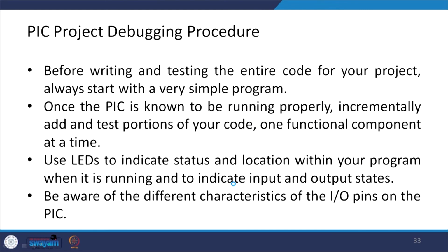For a PIC project, there could be a systematic debugging procedure so that mistakes are minimized. Before writing and testing the entire code of your project, always start with a very simple program. This is always advisable. Once the PIC is known to be running properly, incrementally add and test portions of your code, one functional component at a time.